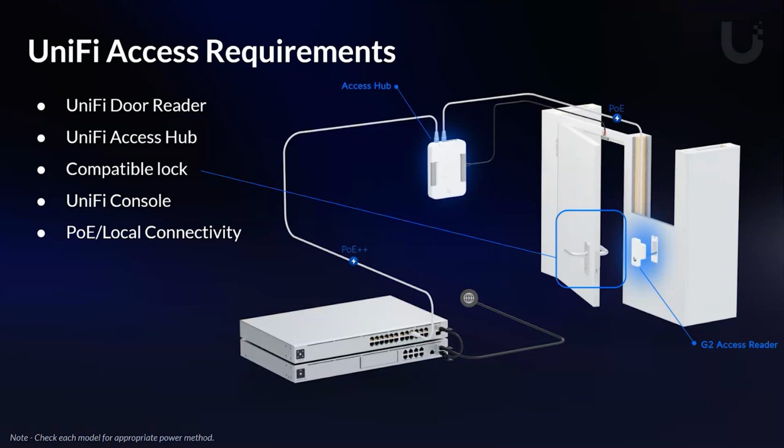It's the UniFi Redundant Power Supply, and basically what it is, you take smart power. We have these cables that connect in the back to all of our pro switches. You can plug it in there to this device, and in the event that the primary power supply fails, it will fail over to the RPS device, the redundant power supply device. So that's what it's there for. And then if you have that plugged into a UPS, of course, too, if the primary power is out, then they can still keep it online in the event of an outage. Just check the specs on that. Make sure you review that. But yeah, that's something we do offer.